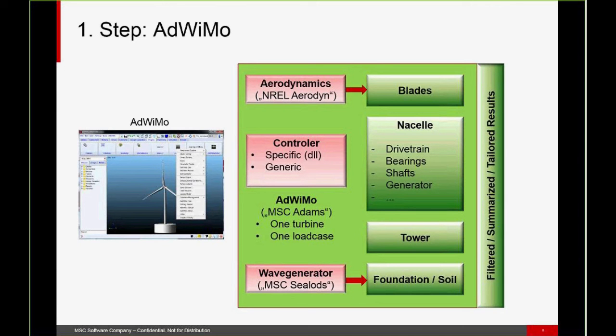You always can describe the components in the nacelle as simplified structures to keep the simulation time very low. This is important if you are talking about certification load cases, if you are talking about real time. So if you are talking about 10,000 load cases, it's better to have simplified nacelle ingredients, I would say, in order to get fast simulations.